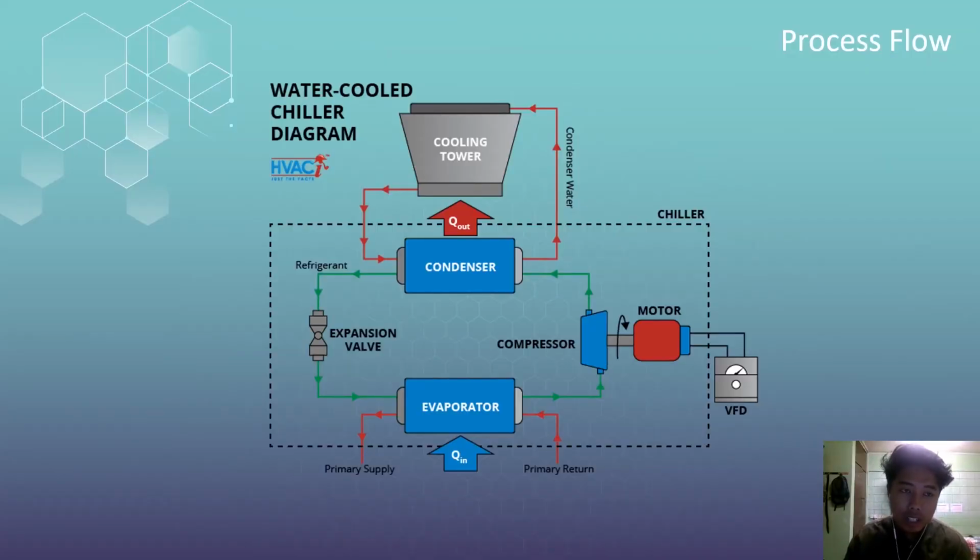So I will be presenting about the findings of our project. We have chosen water cooled chiller as our chiller system. This water cooled chiller features a water cooled condenser connected with a cooling tower. Water cooled chiller can produce more constant performance for commercial and industrial air conditioning because of the relative independence to fluctuation of the ambient temperature.